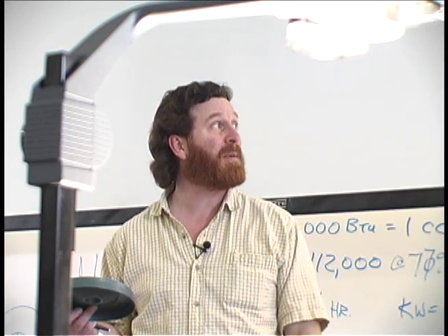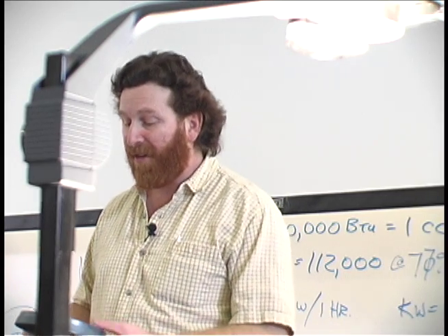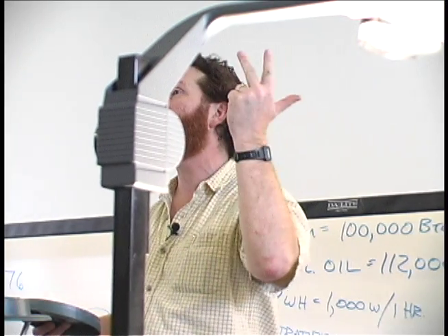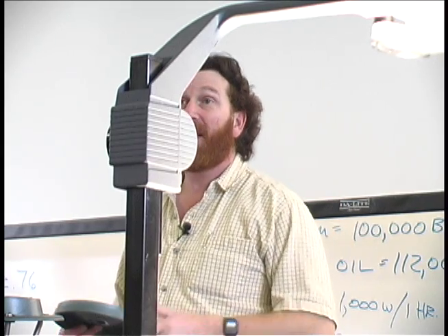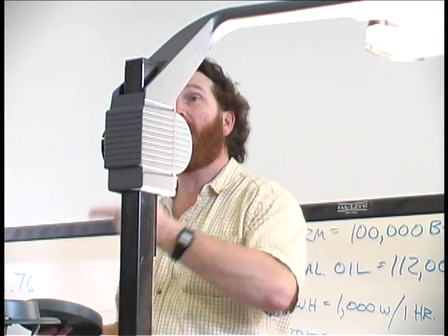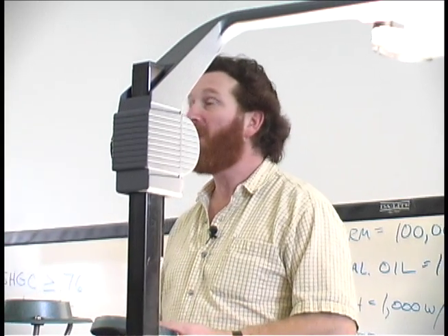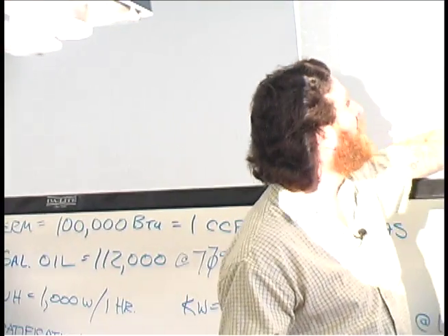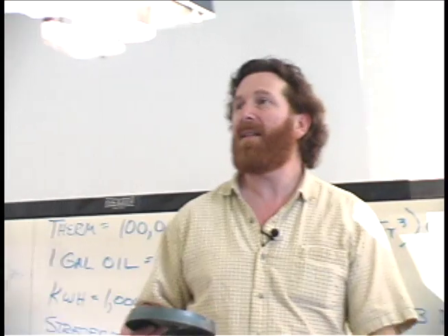Because one of the interesting things about photovoltaics in this climate is that 50% of the output from a PV system in Seattle comes in June, July, and August. 3 months, we get 50% of the output for the whole year. 75% comes between the spring equinox and the fall equinox. So even if you're completely shaded for 6 months out of the year, you're only going to lose 25%. So if you've got some shading down here, this lower part of the graph, it's not that big a deal.